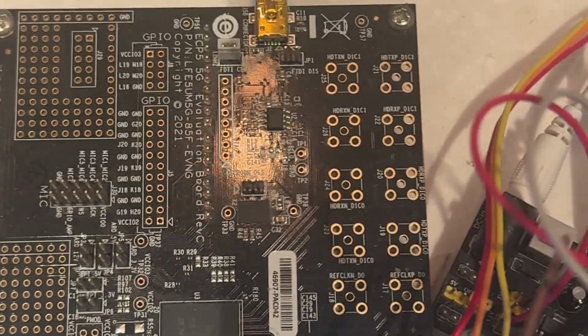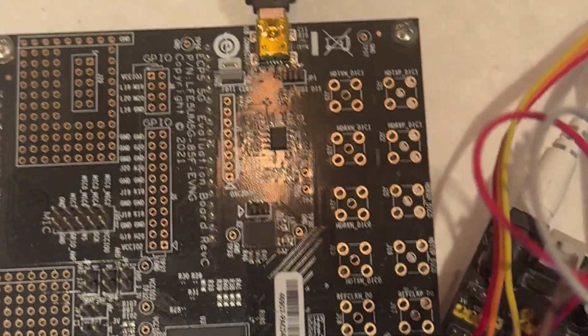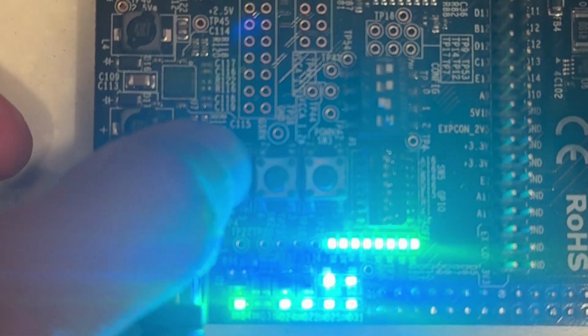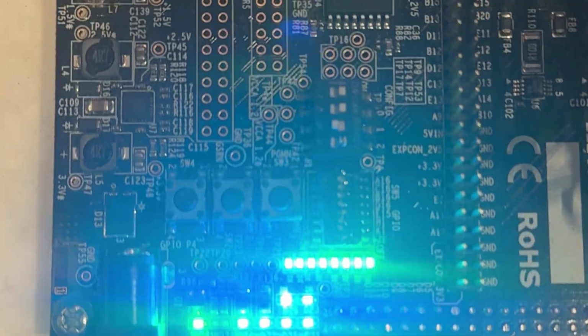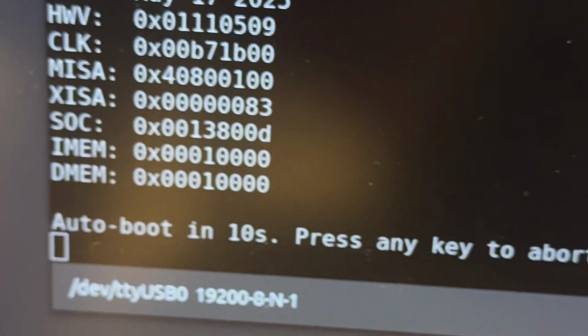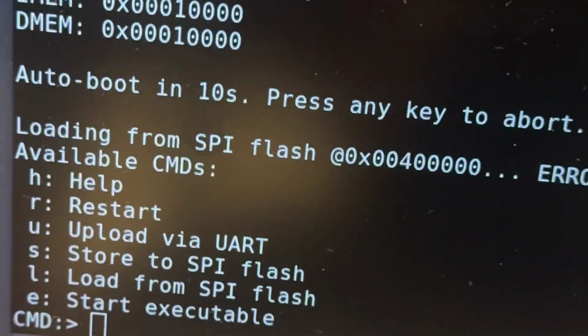I recommend you connect it directly to your PC, but we are also using these UART pins. You can find them on the data sheet, otherwise the board has them labeled well. So match them according to the constraint sheet, and the UART can be connected to a USB hub. For reset purposes, we are using this pin, and the LED blinking shows the NEORV32 is running. And this works. Bootloader, let's start.